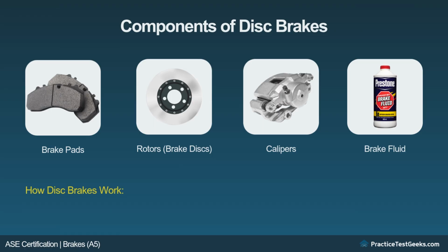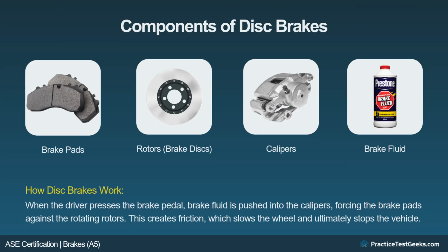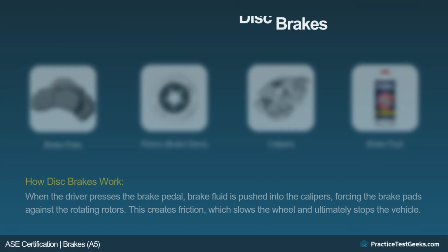How disc brakes work. When the driver presses the brake pedal, brake fluid is pushed into the calipers, forcing the brake pads against the rotating rotors. This creates friction, which slows the wheel and ultimately stops the vehicle.